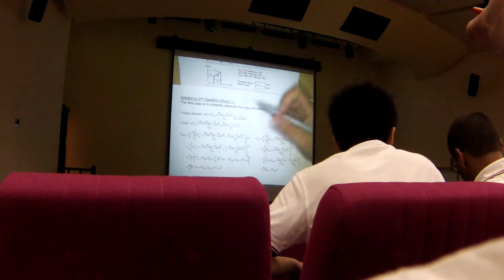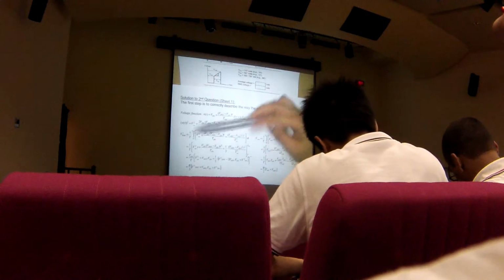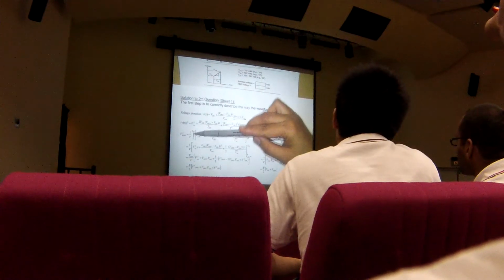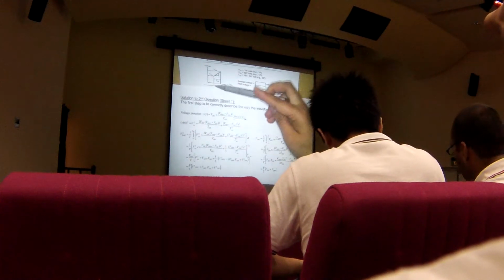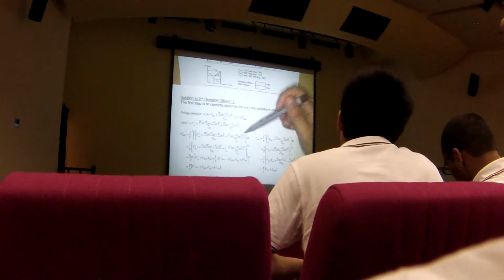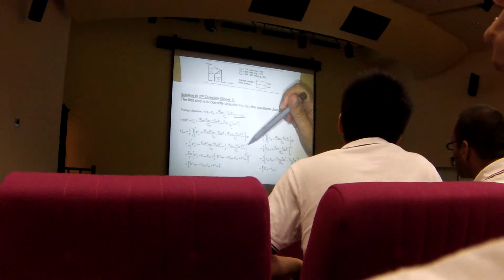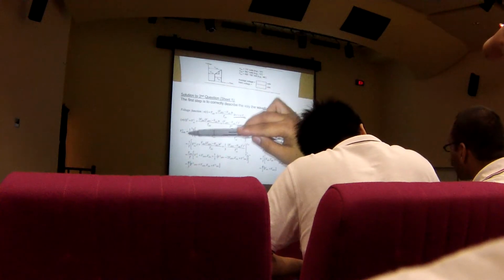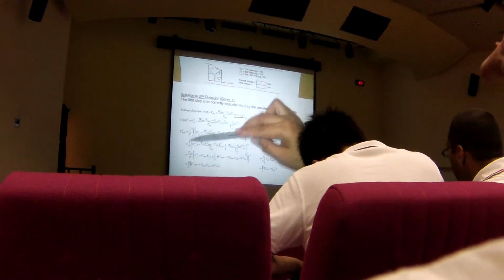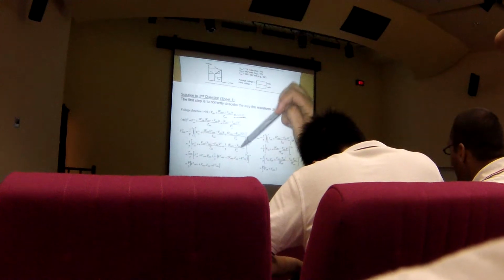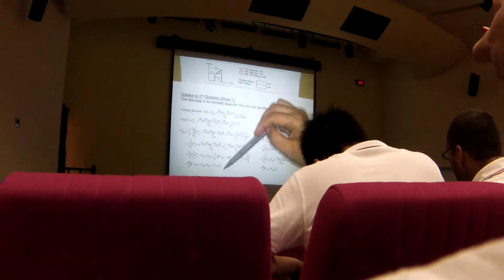So if you know this, you know that for calculating root mean square, you need to have 1 over T integrate from 0 to T on only, because this is only valid from 0 to T on, right? And then you do a V squared of t dt. Root mean square: for VRMS there's a square root, there's a mean, meaning you divide by a period, and then a square, meaning your V squared. If you expand out and simplify, you will end up with this expression.